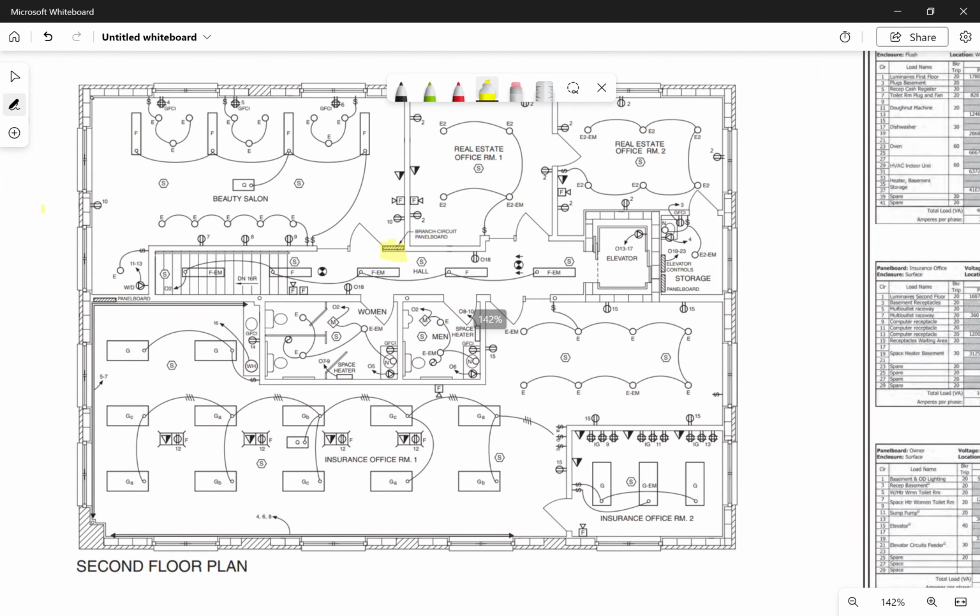When we get ready to calculate how much power this building needs, we're going to count how many receptacles there are in the individual business, so that we can see what size wire we need, how much power it is going to require. We can also calculate it. We can get a minimum number by using the square footage of those rooms. Now this print doesn't have the square footage. We have another set of prints that has our square footage that we're going to look at and reference when we get ready to count our volt amperage for the room.